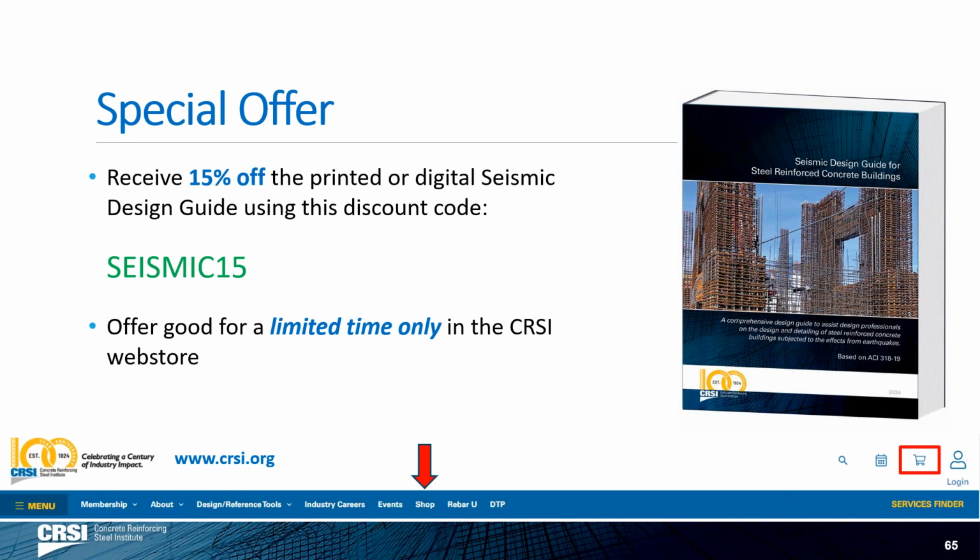Okay, slide 10. Shear stirrup and hoop is 60 KSI, and seismic in special moment frame is 80. Please clarify. Oh yeah, I think I know what you're talking about here. For shear, that's not in a special moment frame, be it a beam or column.